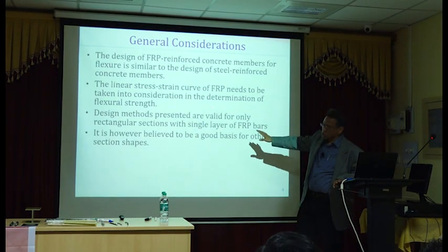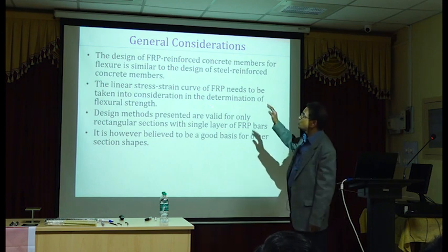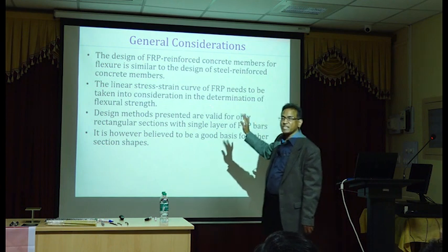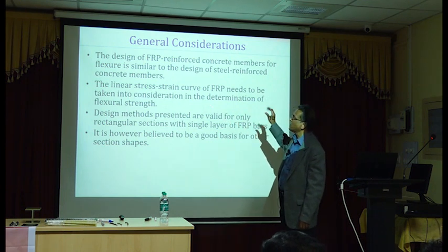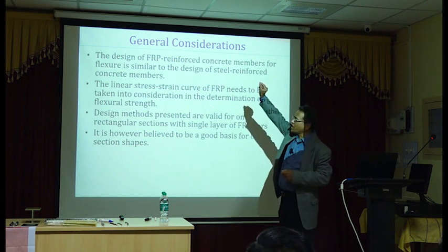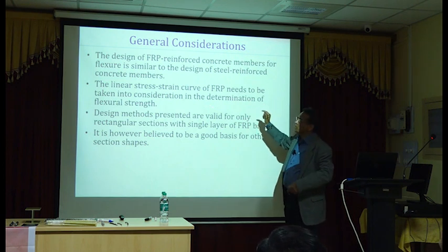Some of this is repetition, so we will just skip it. Not go into too many details. So the design method is very similar to steel reinforced concrete sections. The only difference is we have linear stress strain curve until failure. That makes it a little bit more tricky. So we need to consider that.